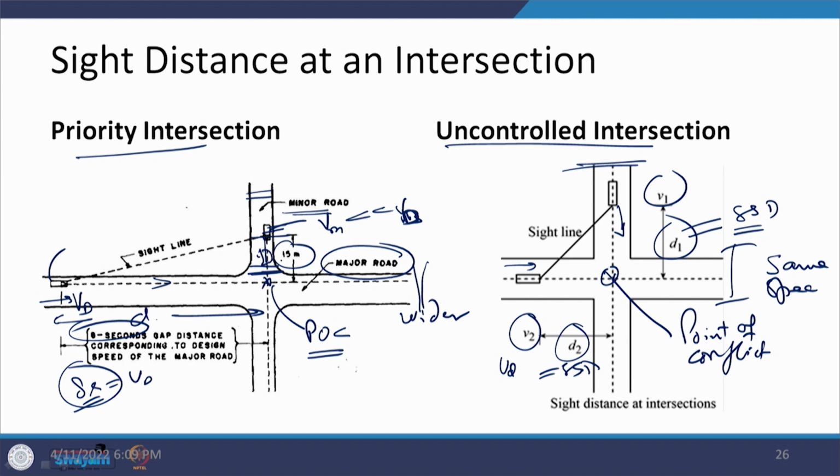here at a stop line. So, I may have a stop line here, then it looks whether there is a vehicle on the major road and there is a gap, then this vehicle can cross and it will come to this location. So, it will start, accelerate, and cross the width of this major road, and this whole process takes 8 seconds. Therefore, the safety margin for this particular vehicle on a minor road should be equivalent to the distance travelled in 8 seconds on a major road.